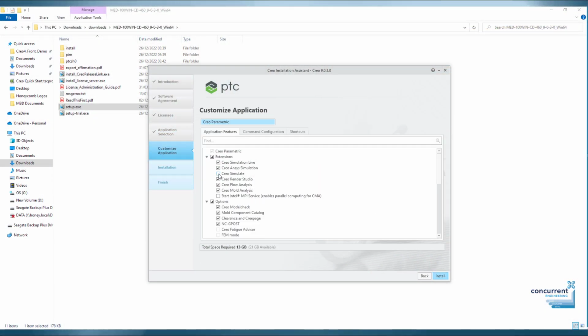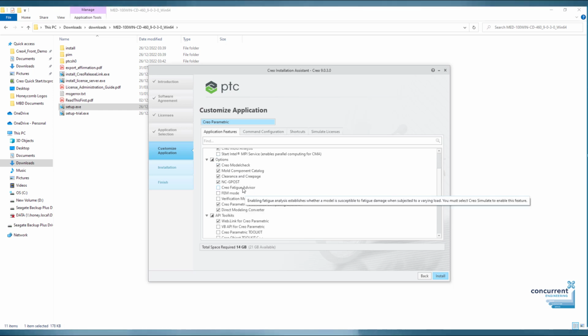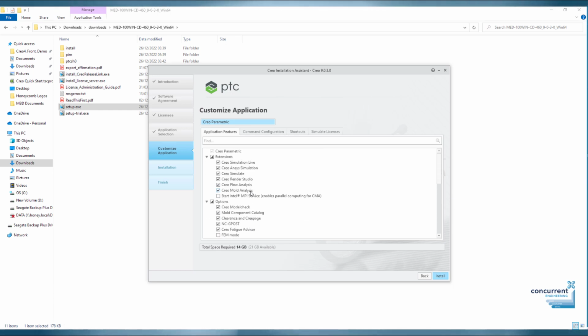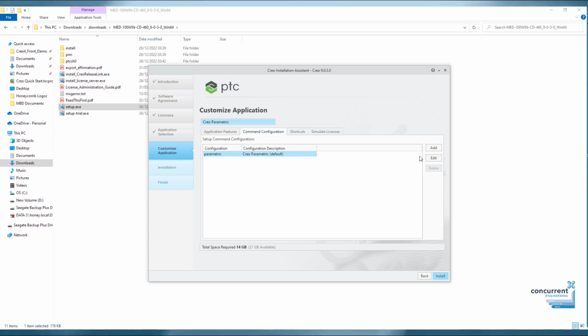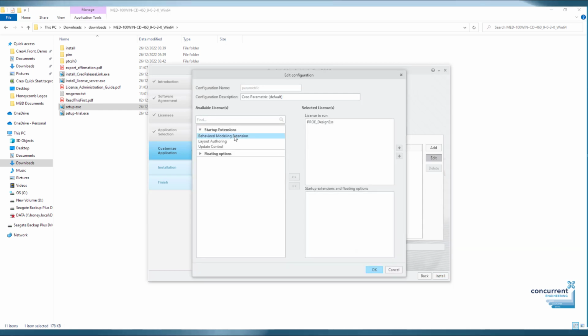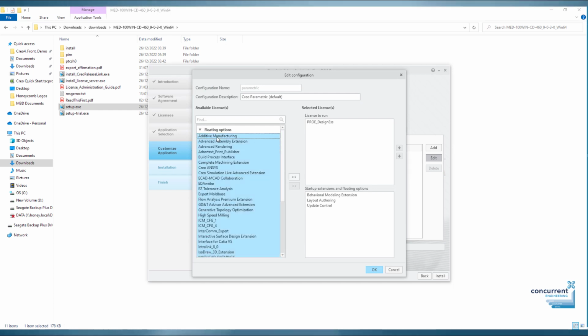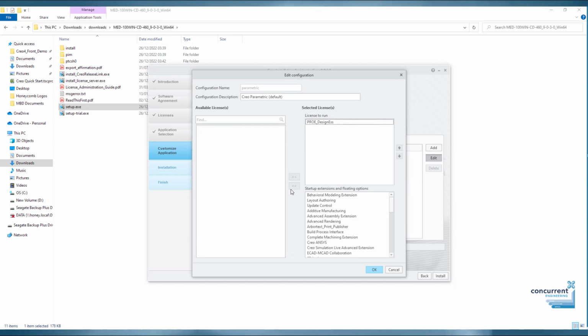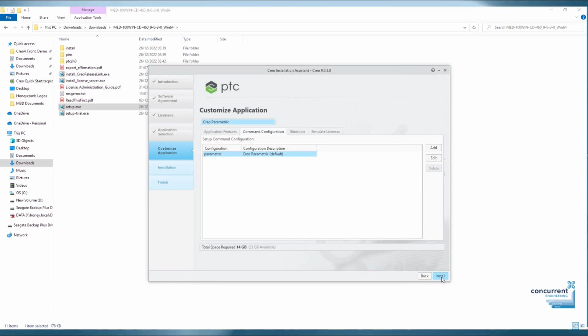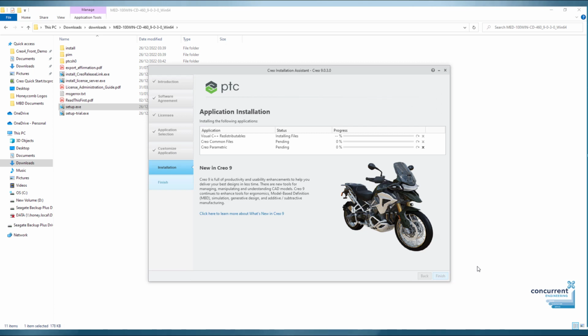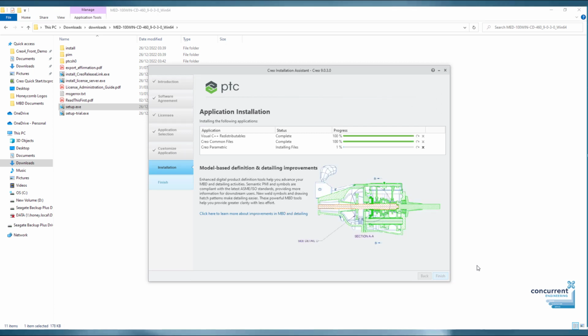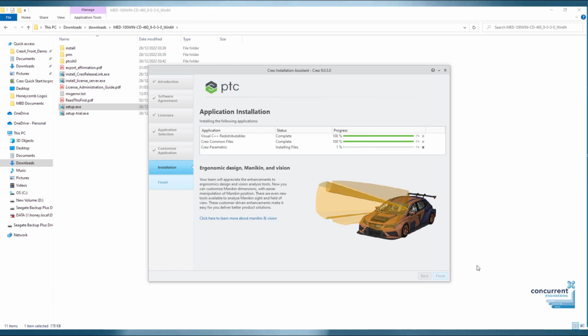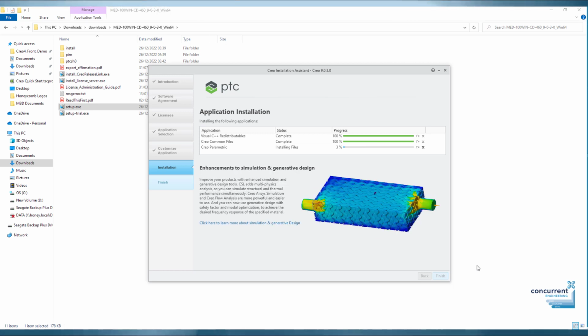Now this working environment is supported in Creo with the use of floating licenses. Essentially, a floating license is installed with central license management software, either on a shared drive or a server. And in many ways the process of getting this set up is very similar to that of the locked licensed installation that we looked at earlier on. So let's take a few minutes just working through installing your floating license. Now a floating license can be simply installed locally onto your machine if required. In fact, this is how my license is on my own machine.